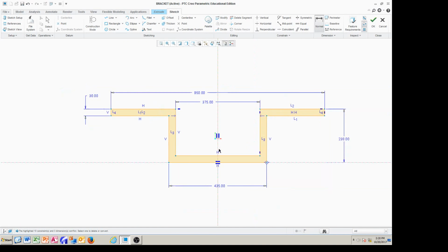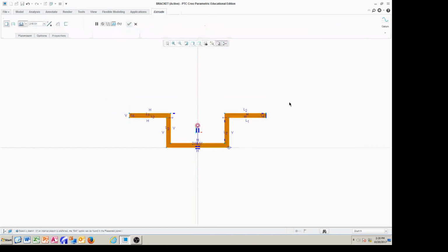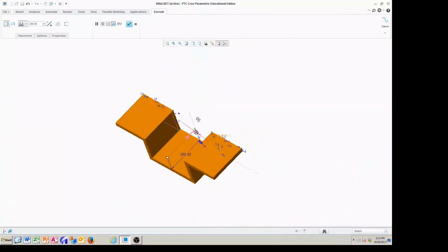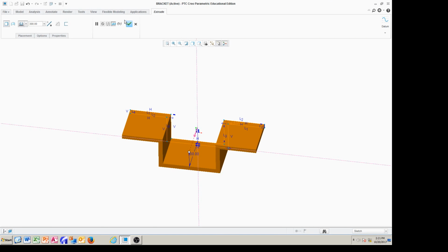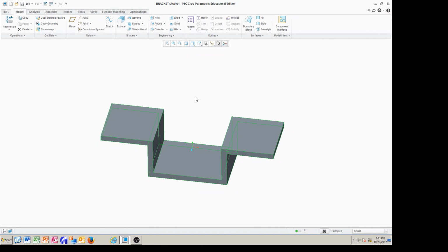Okay, I think we are all set. Look around, check to see if everything is good, and all the dimensions, and there we go. Then let's just complete this. All right, and the depth for this is 300. We're going to just type 300, and then hold the middle mouse button and rotate it. You can see that you created a solid model. Excellent. This is fun now. So far so good. We have our solid model.